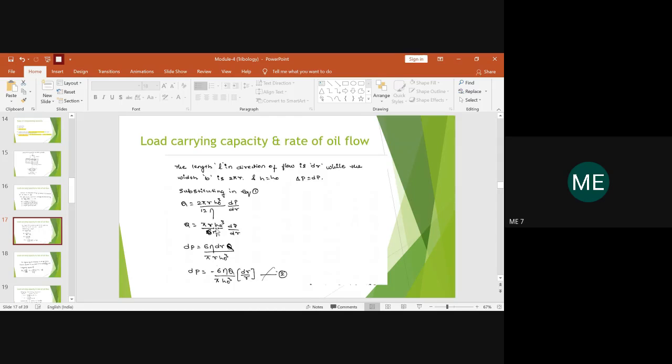So from this equation, now you have to try to figure out what is the value for change in pressure. And hence you will take dP outside towards your left. So other things you will retain towards your right hand side. So dP will be equal to 6 mu dr Q upon pi r h naught cube. Okay, so first you will get the equation for Q. So then you will try to get the equation for change in pressure. So dP will be equal to this.